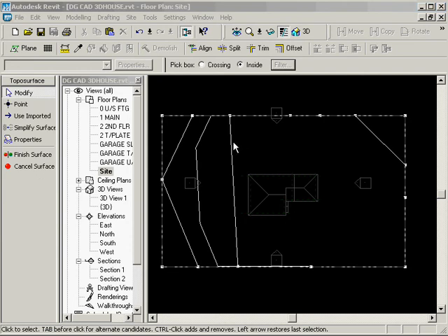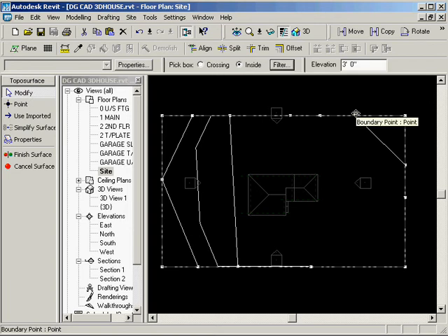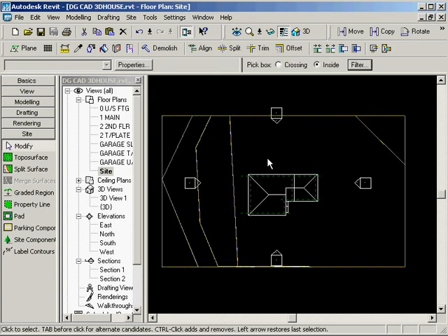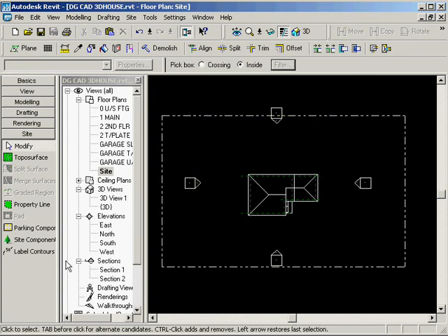So inside of here, I had a quick look, and I believe I've got a slight problem here. If I go into modify, my elevation offsets should have been negative numbers, -3 feet below 0. So I'm going to cancel my surface here, and I'm just going to click on this and delete it. And I'm going to try this again.